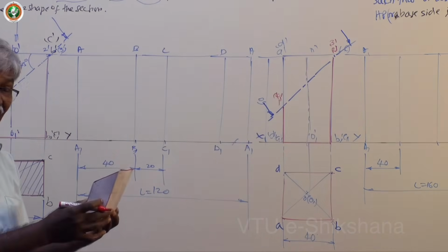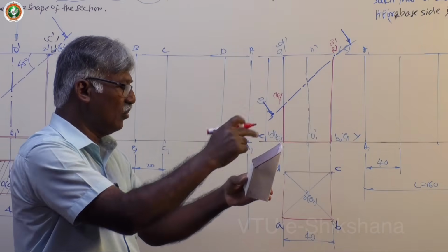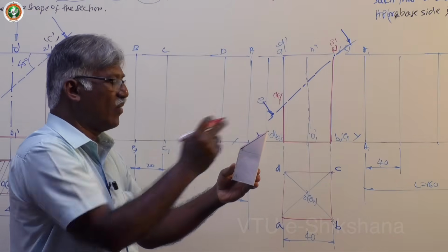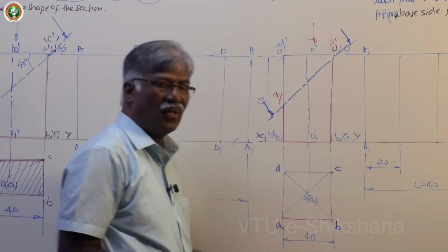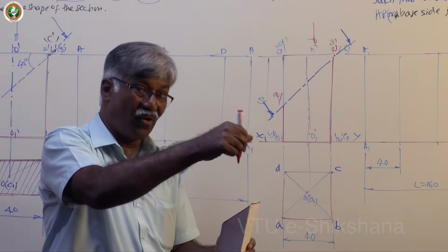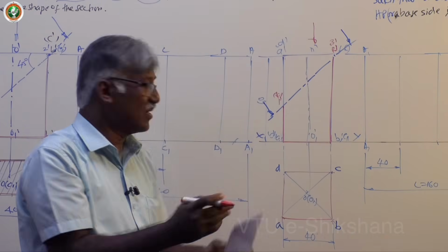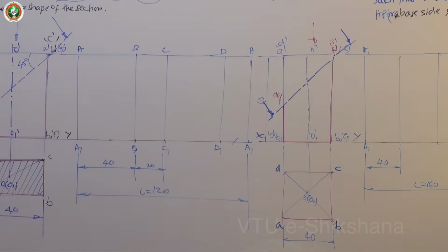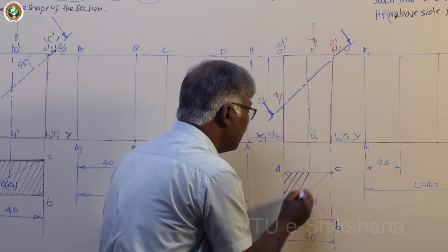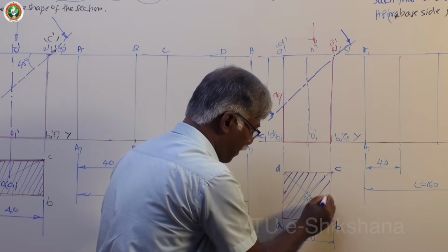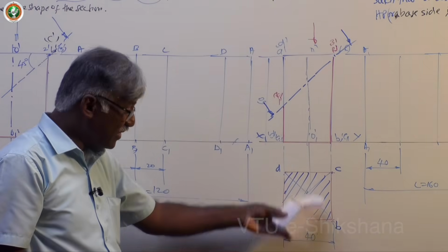Similar to a rectangle, the only change is longer edge, smaller edge. Here all edges are the same. Same thing, 1, 2, 3, 4. 1, 2 are visible, 3, 4 are not visible. Then what about the section? If you look from the top, you get a square only, because all sectional sides are coinciding with the lateral surfaces. So this itself is the side, section at 45 degrees.